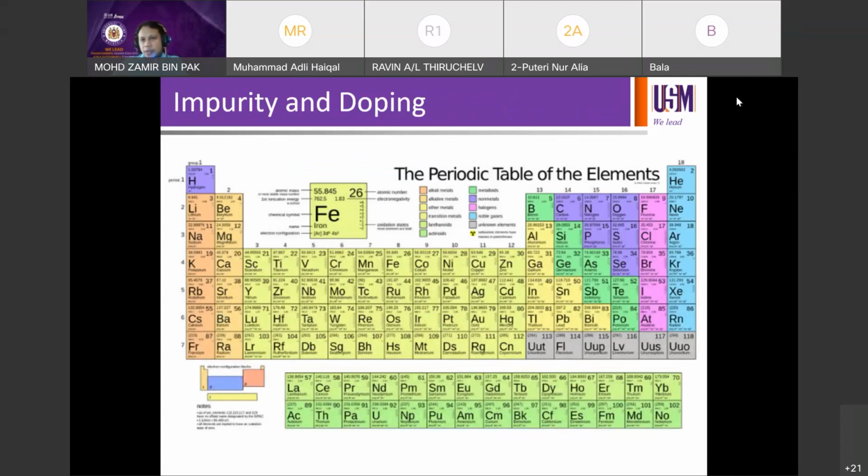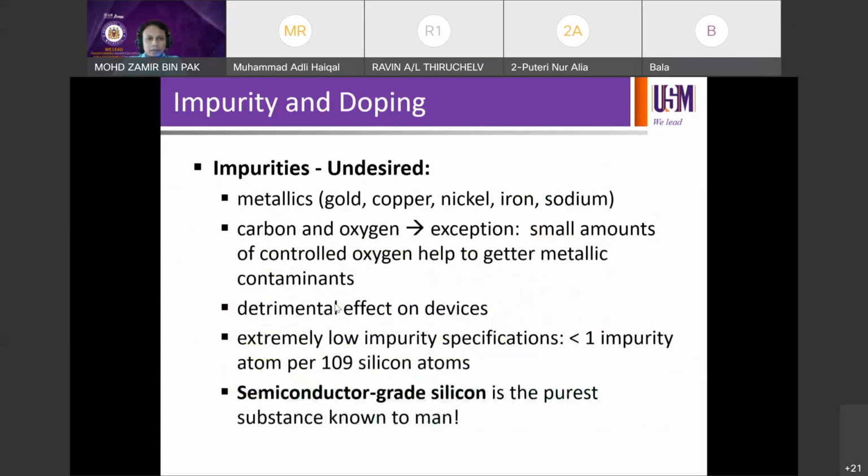So we mentioned and discussed briefly about doping. We discussed a little bit about intrinsic, extrinsic, but we haven't gone through the details just yet, right? So impurities can be incorporated into our semiconductor materials. Okay, so we discussed briefly about group 3 and group 5, which can be incorporated into, say, our silicon lattice in order to alter conductivity, right?